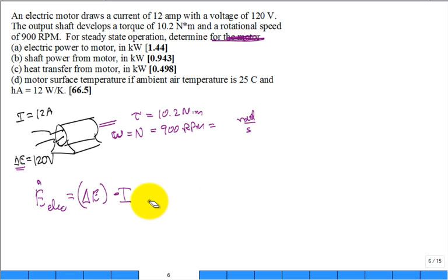But anyway, power factor, tuck it away. It's really important. You have a shift between the voltage phase and the current phase. They're not in sync. If you put the AC power to a resistor, power factor is 1. But when you put it to an induction motor, you get a large shift. That's why you have capacitors to help compensate for the inductance in the motor. But that was a digression. But this is what you want to do right here.